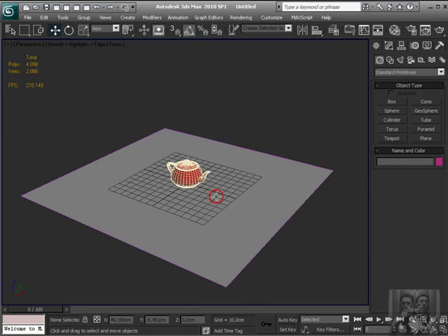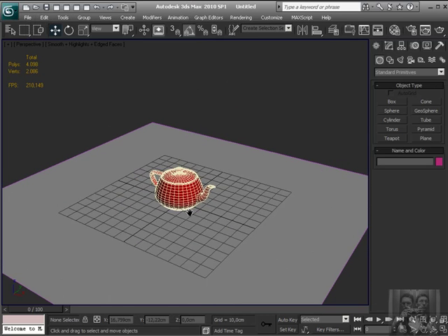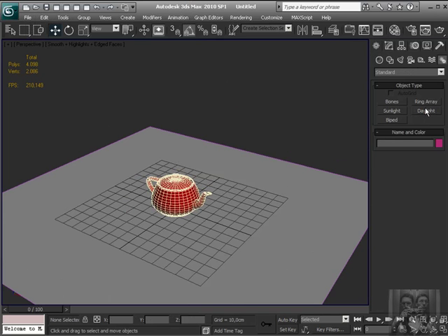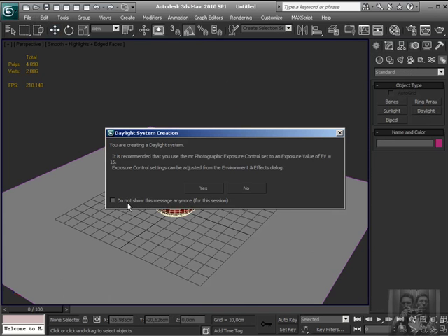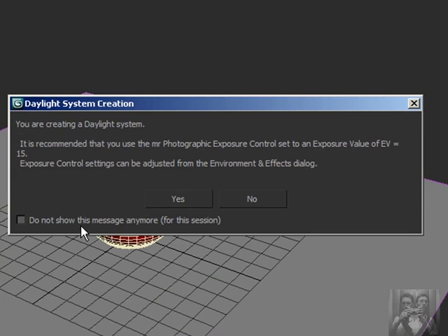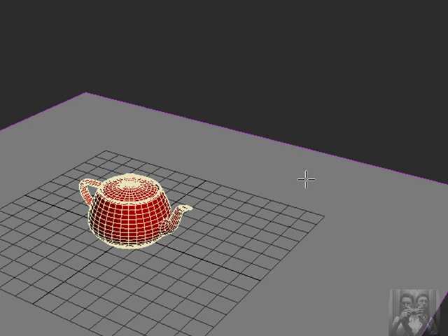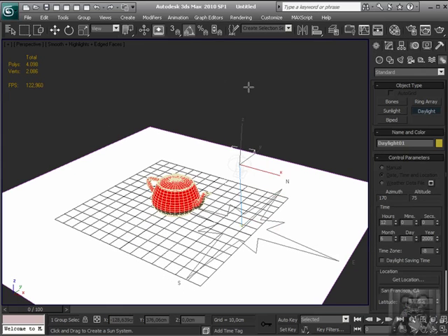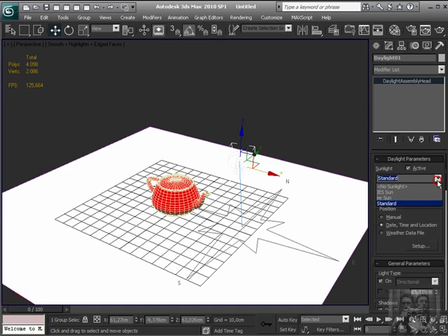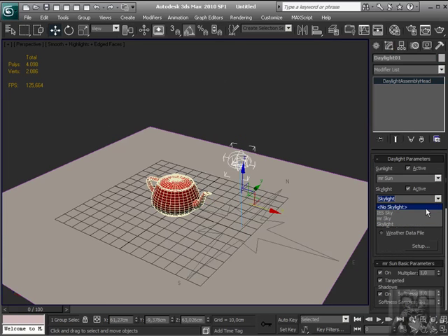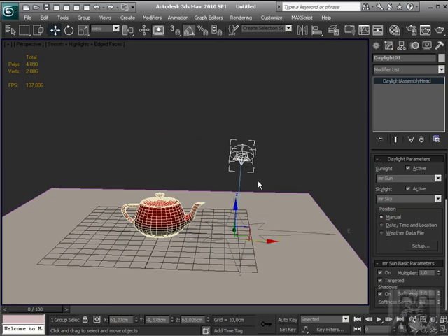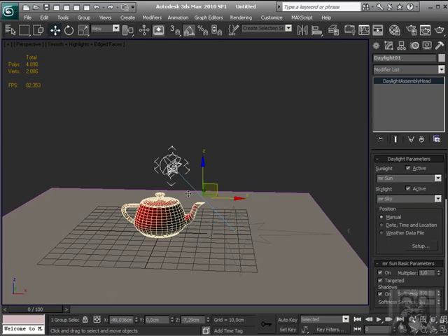Okay, when you render, you can, for example, use daylight. If you use more, you can check this option, which is very important because it creates the exposure control and gives Mental Ray Sun and Mental Ray Sky. Yes, physical sky. Okay, and I choose manual so I can take this and move it more.